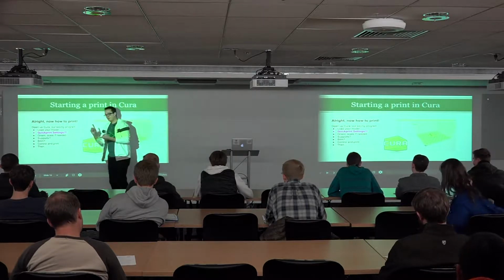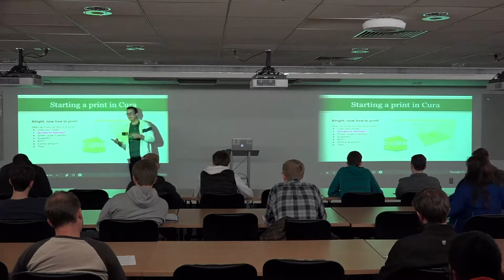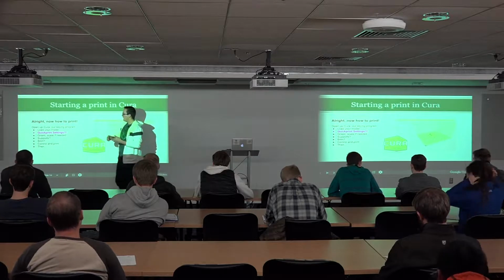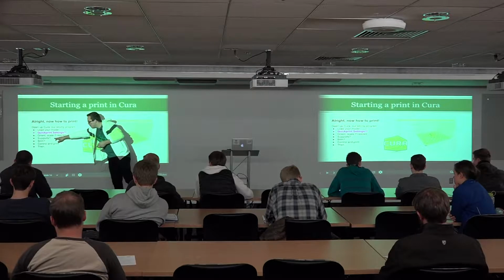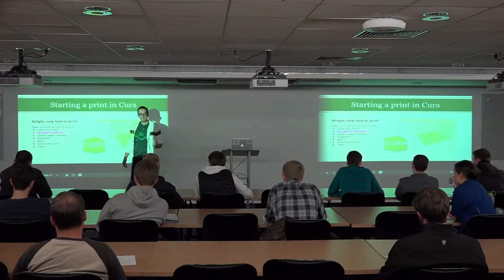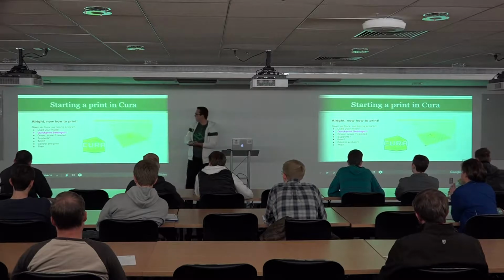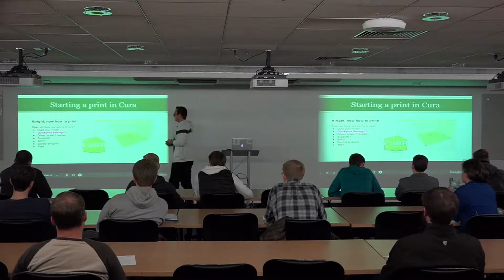That will just ask you what material you're using. Do you need it to be fine or fast? The higher resolution prints, of course, take longer. And it gets you some of those simple settings. It'll ask you if you want supports or brim. We talked about supports. This little octopus here is completely flat on the bottom and he's got no overhangs, so wouldn't need any supports at all.